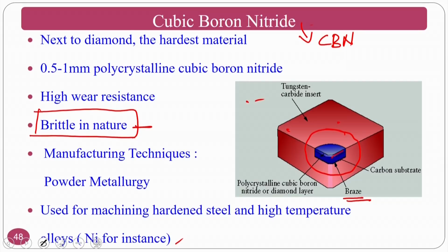The tool takes care of only 15% of the heat, out of which the CBN has low thermal conductivity. That means the top edge of the cutting tool will experience most of the heat and it cannot conduct towards the bottom side. So, there is very little chance of it going down. If it is not maintained properly, it will go off.